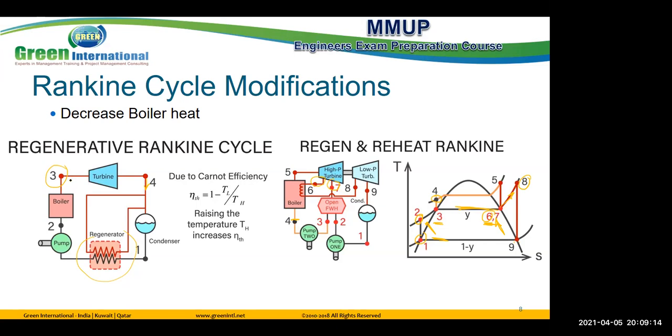But this is the output from the turbine. So I already collected the energy I need, but still have energy. So instead of just releasing it to the surroundings, I make a heat exchange here to increase the temperature of the flow coming from 1. We are preheating feed water basically. Yes, feed water, but this is a closed feed water heater. Yeah, this one is an open feed water heater. Exactly. Okay, thank you.